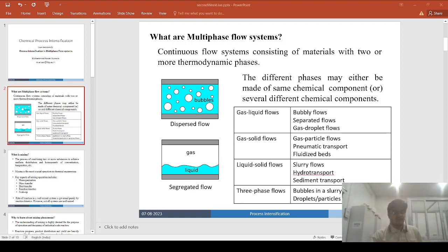A specifically designed gas liquid inlet section with narrow channels provides rapid contact of the gas and liquid reagents. And in order to achieve uniform flow, the pressure drops in the inlet gas and liquid sections exceed those in the individual reactor channels. Basically, if you perform the bifurcation, you will have a much higher pressure drop than in singular channels.